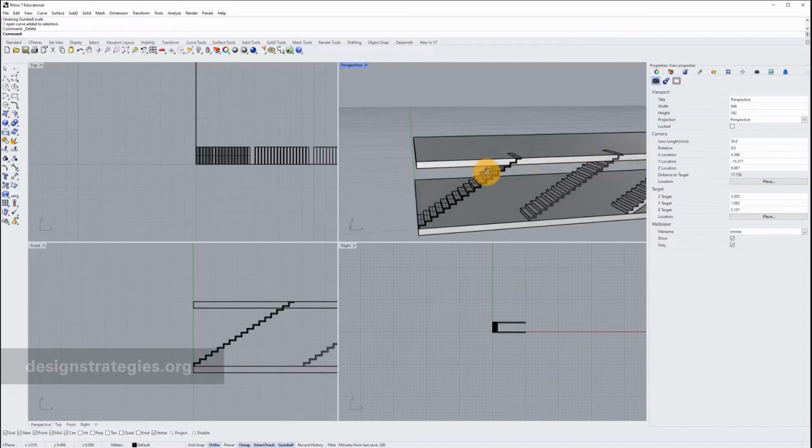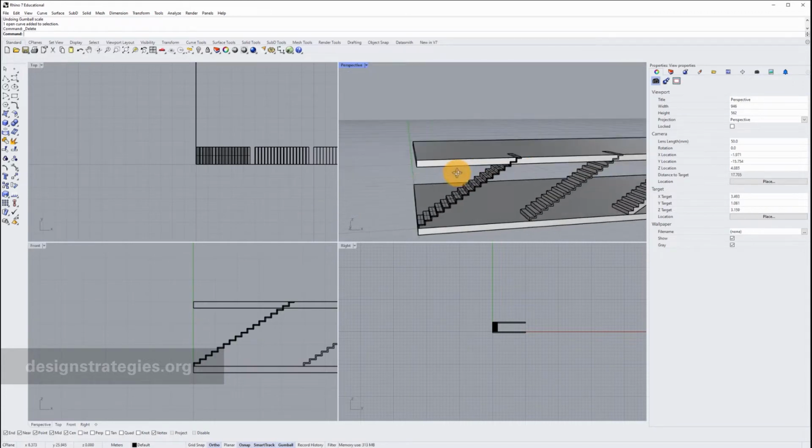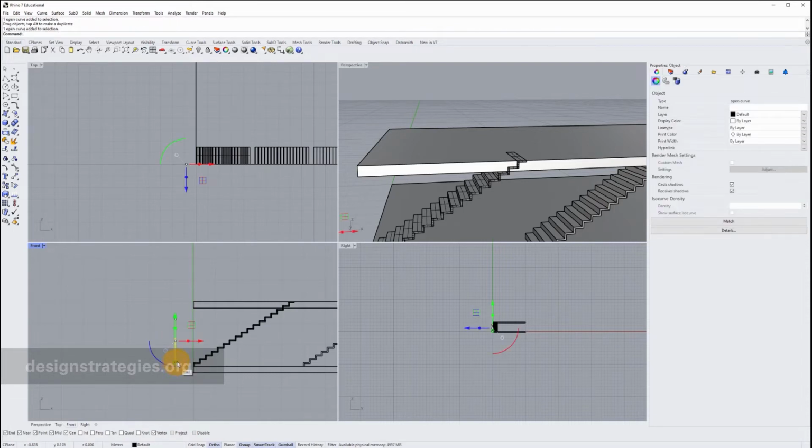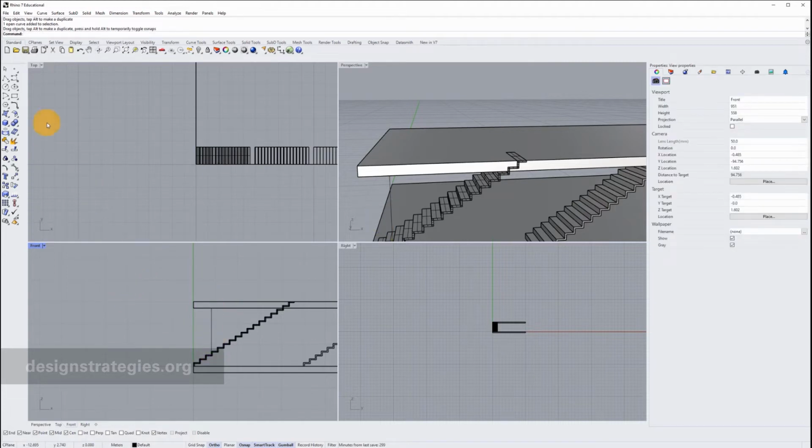It's obvious that you can't walk up these staircases so fast, so you have to create an opening in the top floor. And we just create one human being just as a line. I just enter 2 meters and finish with right mouse click, and then I can move this. I just grab it here, and I can move this up my staircase, and you can just see, starting from this step, it is difficult to pass when you're taller than 2 meters.